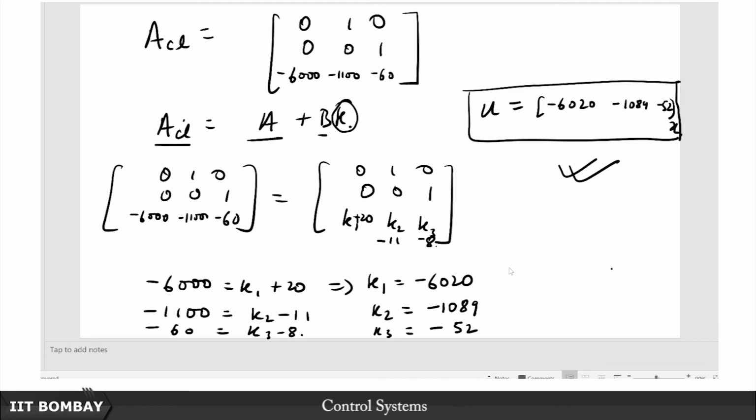The error in the observer decays means that x hat is almost equal to x. So if the dynamics of the observer is not significantly faster than the dynamics of the plant plus controller, then the states that we will be thinking of using, that is the x hats as the proxies for the actual states, may not already have converged, the error might not have converged to 0 already. So in general, the good idea is always to place the observer poles much deeper into the left half of the S plane than the poles of the controller, and this is not a problem because after all the observer, as I said, is a software, it is a piece of code. So there is no real actuation going on over there. So you have no hardware to take care of, right. So, that is one thing.